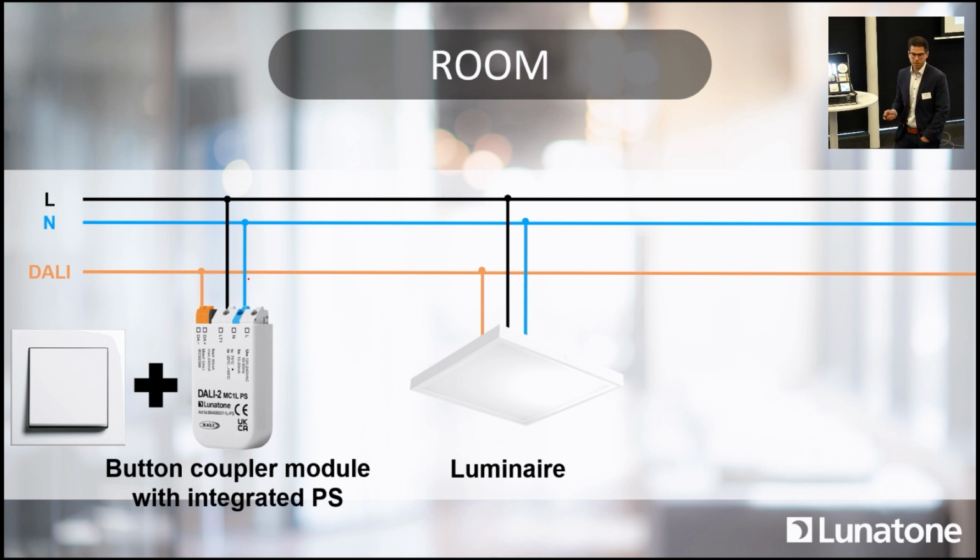So it knows already when I press input 1, all the lights should go to 100%. And by the second button press, it's a kind of toggle mode. With the second button press, everything goes down to 0% again. It will be sent as broadcast, and all the DALI luminaires already work with that without a configuration.